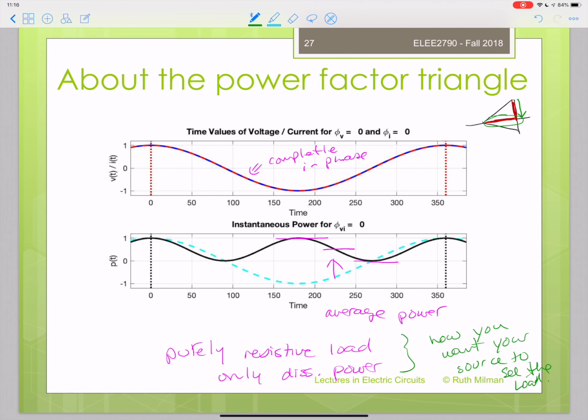And by the way, if you think about what we've done in terms of our circuits, we've always talked about the resonant frequency. That resonant frequency omega squared equals 1 over LC. Well, in fact, if you use your resonant frequency and you set up the right capacitors, that's essentially what you're doing when you do this power factor correction, except it's easier to do the math in this case because you don't have to worry about actually figuring out what the complex impedance is of your entire load. You very simply look at it from the perspective of the source, and you take a look at the complex power that's being used by your load, and you subtract off by doing the opposite on the other end.